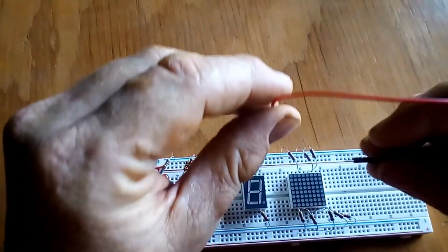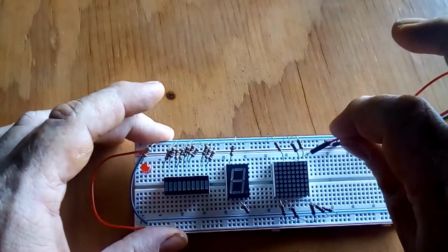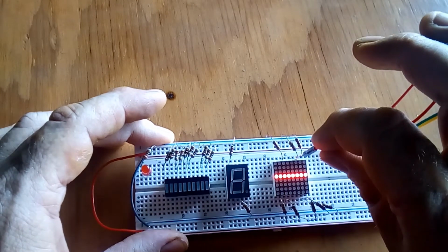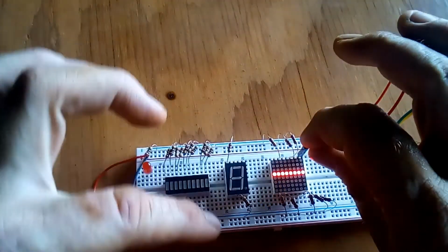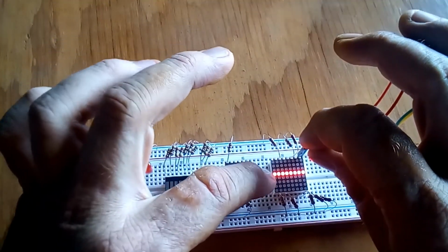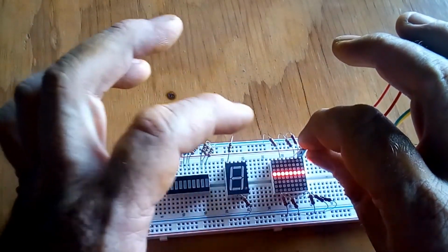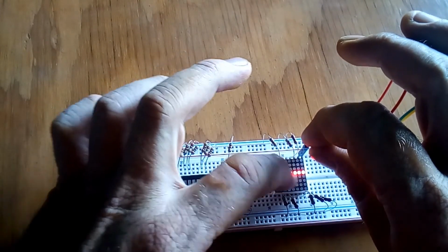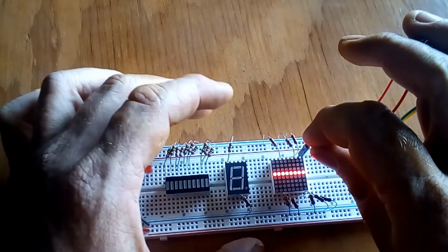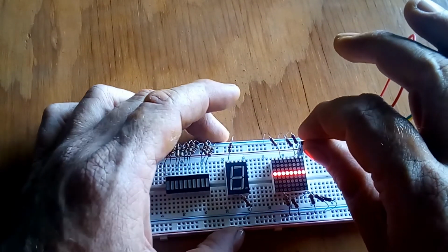Okay, so to see that in action, I'm going to stick this wire in the hot rail, and then I'm going to hit each one of those anodes in turn. So pin 1 here, you can see turns on that row. And then we would multiplex through those columns, or multiplex through the rows. There's another video about multiplexing. I probably could have used this component for that video. But you can see pin 1 turns on that row of LEDs. And then when we multiplex through it, we can set up the pattern we want.